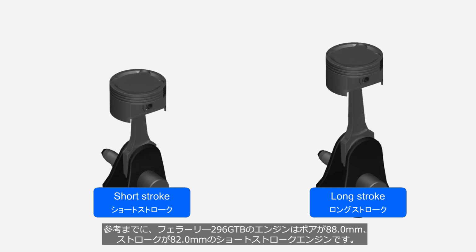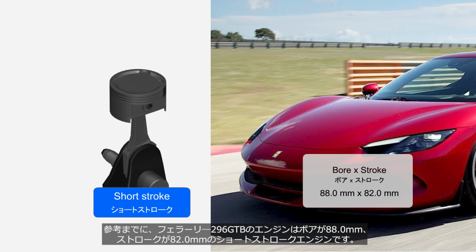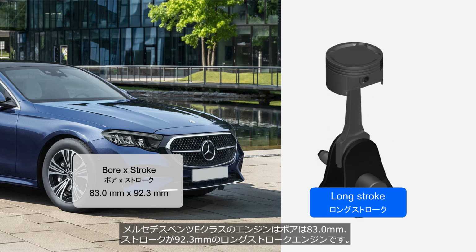For reference, the engine of the Ferrari 296 GTB is a short-stroke engine with a bore of 88 mm and a stroke of 82 mm. The engine of the Mercedes-Benz E-Class is a long-stroke engine with a bore of 83 mm and a stroke of 92.3 mm.